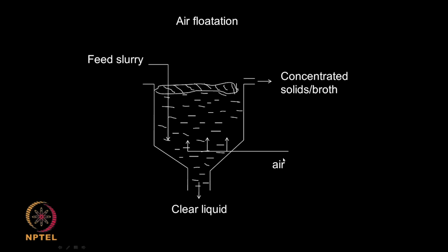So, here you require air. The advantage of this method is you are not adding extra chemical and contaminating the setup. You are just bubbling air into it, so that the fine particles are trapped in the air, which can be skimmed out. So, this is much more advantageous than adding a flocculant or a coagulant. But of course, in very large systems that may become a problem, so it is much easier to add a coagulant. In water treatment especially, they generally use a coagulating agent.